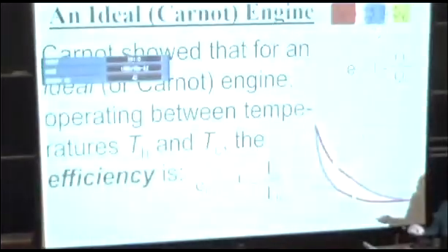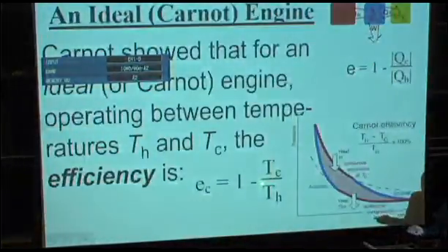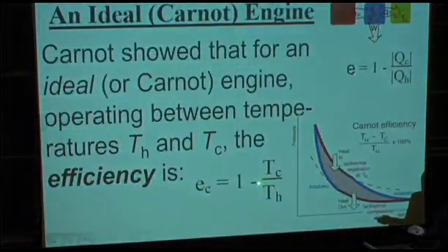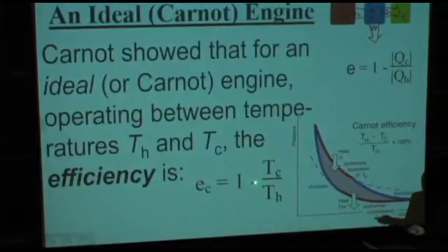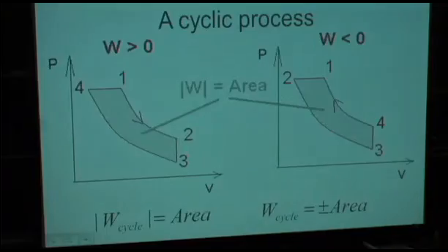People forget about this very often. When calculating the absolute efficiency, you must use the absolute temperature, not Celsius, not Fahrenheit. Only absolute temperature works.